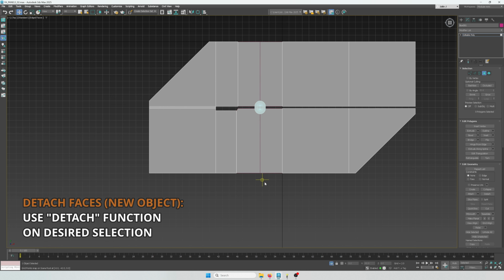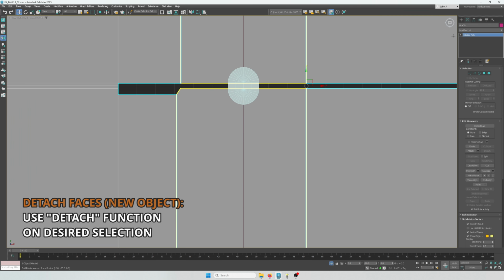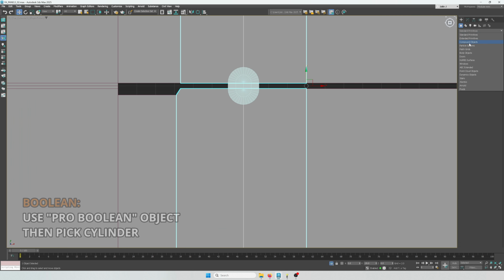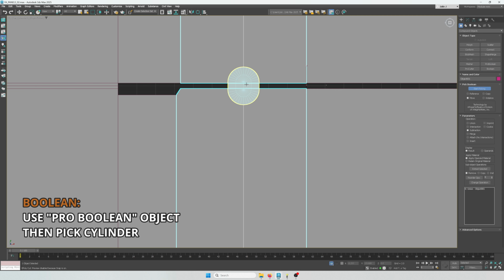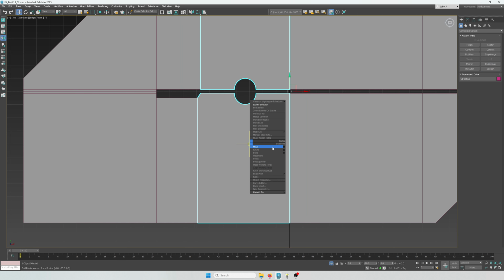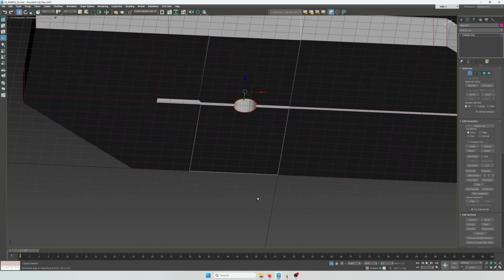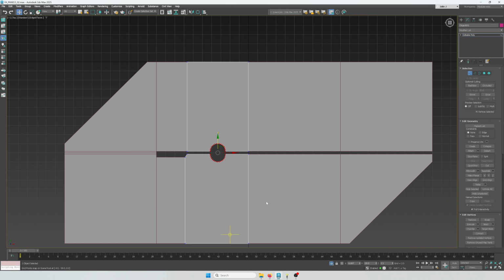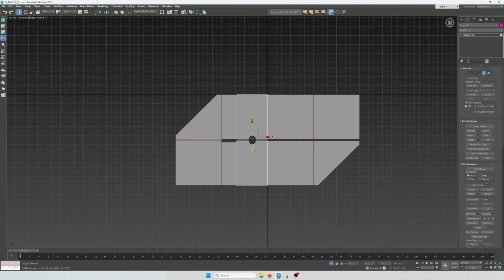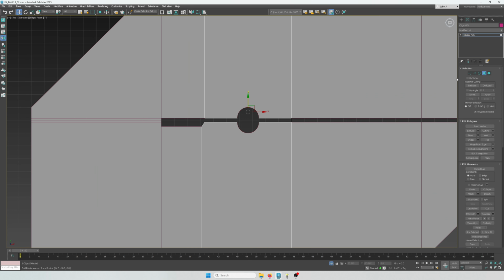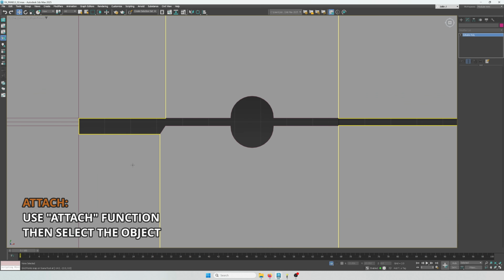3D Max has a tendency of creating some unexpected issues with booleans, so I tend to separate the damage in case something happens. As you saw, that vertical edge suddenly disappeared. It's okay, we're gonna put it back later. With the Boolean operation completed, we can reattach the model.